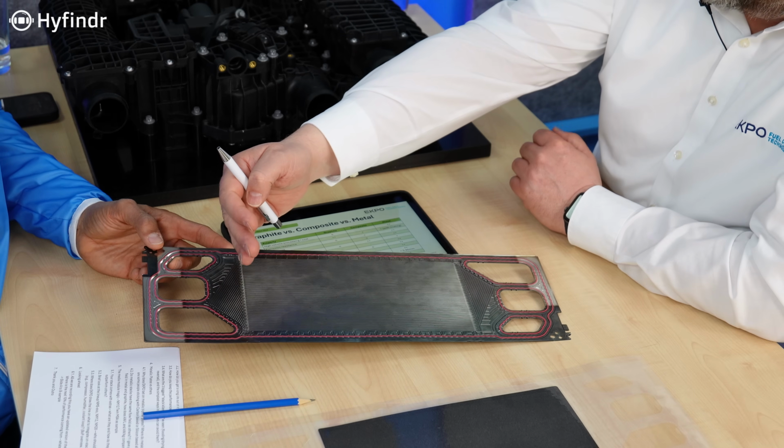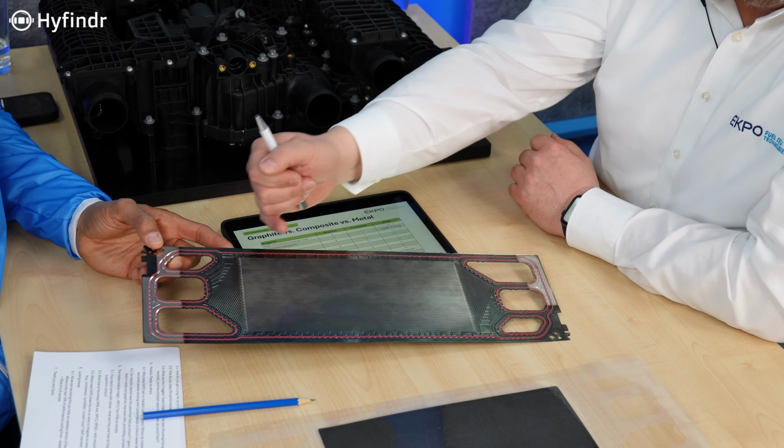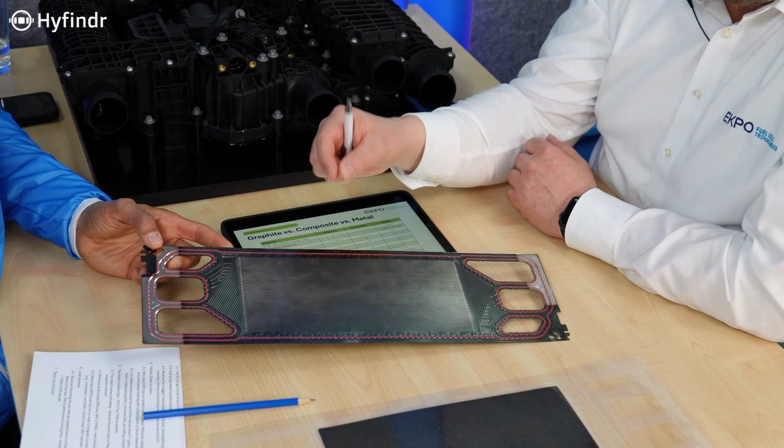And it's also a limit, because you have to push the gases through, and also you have to remove the water. Sometimes they form liquid droplets, and they have to be removed. If this channel is too narrow, they get blocked, they get stuck in the flow field. And if you have a droplet stuck in the flow field and there's no hydrogen beyond that, you will have a severe issue with the membrane behind that droplet. So you're saying there's a limit as to how small they can get. Okay, cool. Thank you for sharing those insights. I'm sure there are applications where the other ones will fit better, maybe stationary or whatever.